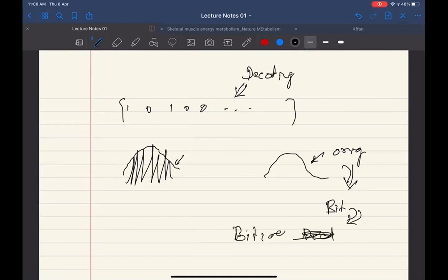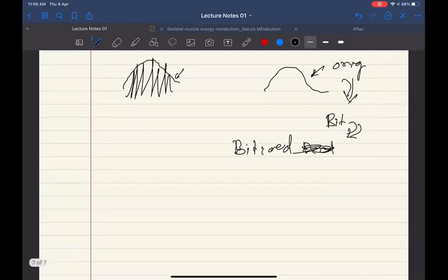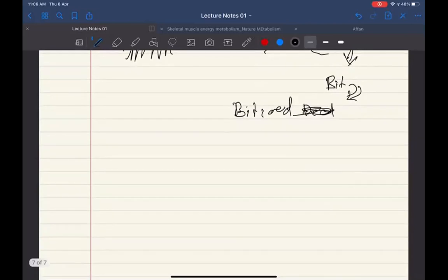It is still not decoded, but you received the bit form. You extracted the bits from the modulated signal. Now we have to recover the data from it. Once you have 1011001101001, whatever it is, remember that in the encoding process we had defined 4 bits for each sample, and the leftmost bit was the MSB, the most significant bit, and this one would be the LSB.